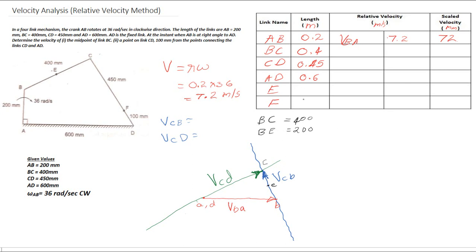So from the velocity diagram we can measure the dimensions of these vectors. Upon measuring this particular dimension, it is found to be between 46 mm and 47 mm, nearing 47 mm, so I am taking this dimension as 46.8 mm.